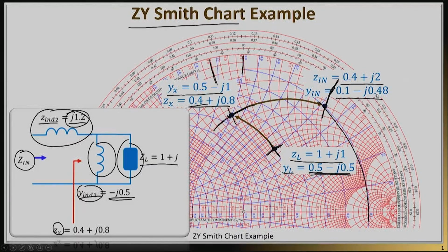So again, the important part here is for you to be able to practice. So practice as much as you can with this type of simple problems so you can feel comfortable managing both series components as well as shunt components. In series components, you're adding impedances. In shunt components, you're adding the admittances.